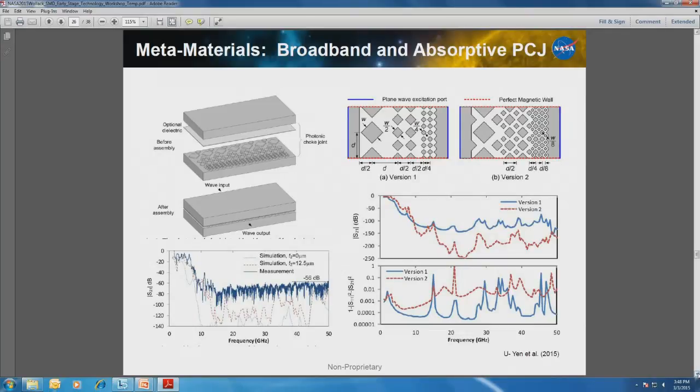was built at 300 gigahertz. Bolometers essentially absorb any light that hits them, and that's a problem. When you're building waveguide-mounted bolometers, the low side is pretty well protected because it has a waveguide cutoff. All the light is reflected away. But on the high side, where you're multi-moded, you need to worry about what's happening over a huge bandwidth, because the blue leak light that gets in can degrade the performance of your detector.